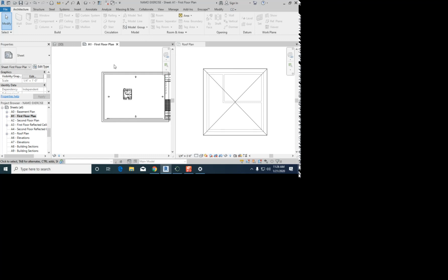What should your wall height be set to? Is it a number? And what is the roof? So tell me what is the term for the roof? It's called a level. Yes. So your wall heights should be set to levels. Not necessarily a numeric number, but it should be set to a level. So it always corresponds to that level. So when you change that level, the roof, up or down, it moves with the roof.